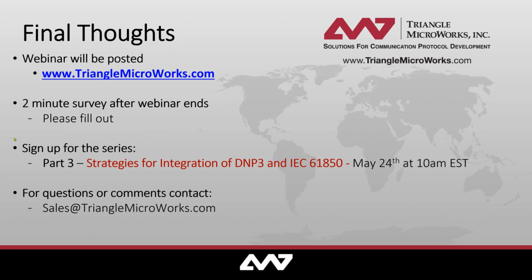I mean, the CID file describes one IED. As I just discussed, it describes the IED and what it has to subscribe to. There is a process of getting information from two substations where the devices have to communicate with each other. There's a process defined in SCL through what we call an SCD or System Exchange Description file.